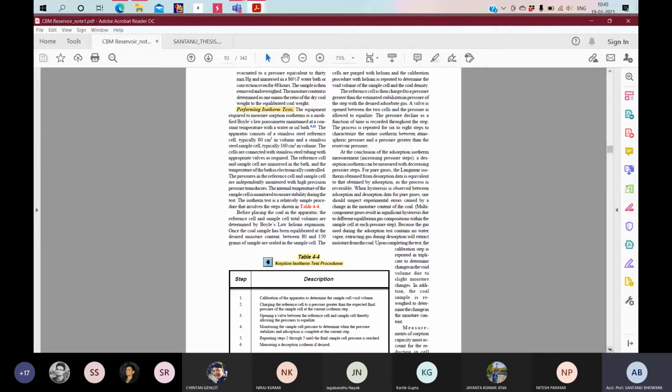Okay, and from the material balance equation, using the real gas law, PV is equal to nRTZ. P is the pressure, V is the volume of the gases, small n is the number of moles, capital R is the universal gas constant, T is the absolute temperature in Kelvin, and Z is the gas compressibility factor. What is the gas compressibility factor? With pressure, how much the volume is going to be affected, how much compressibility, related to bulk modulus.